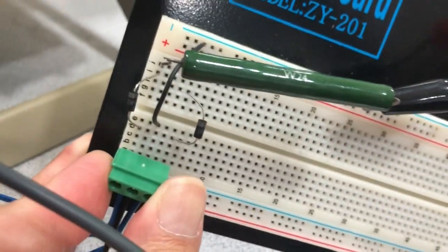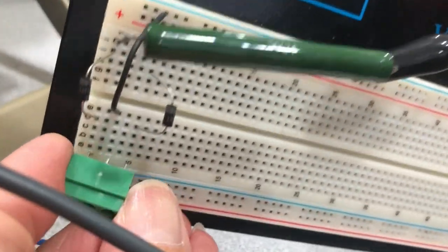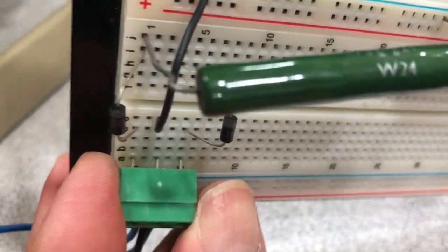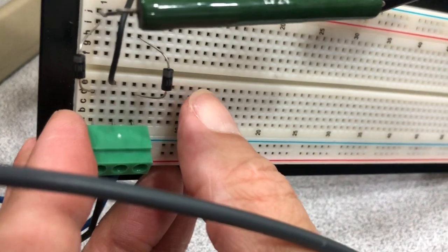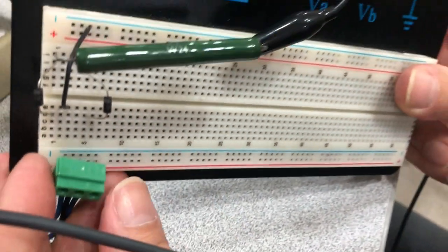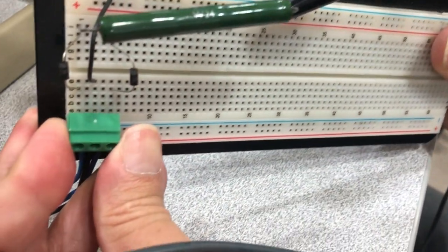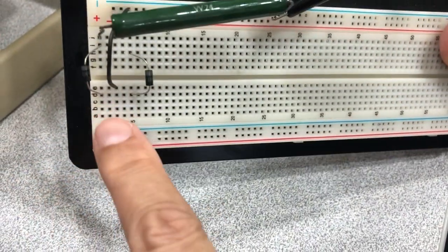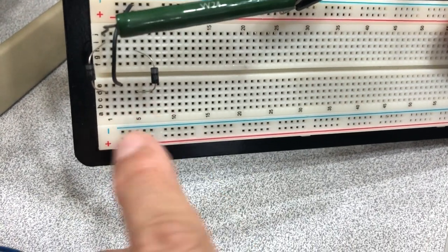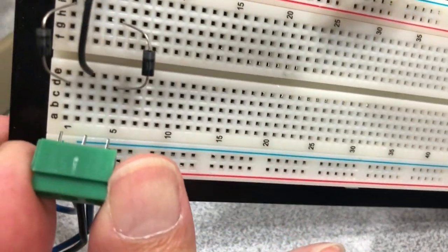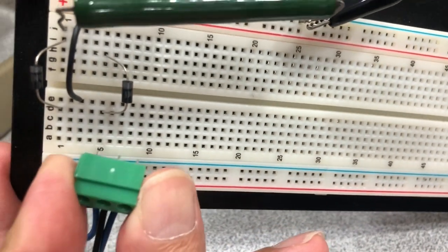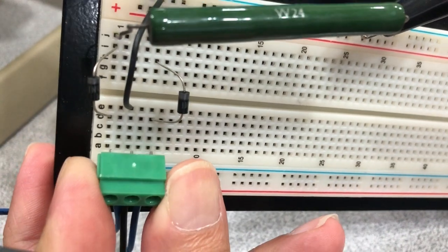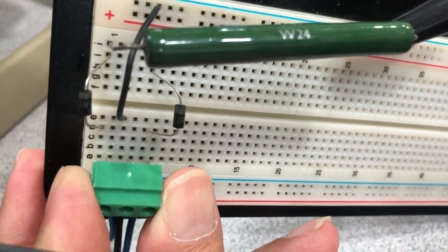The center tap, I have to skip one to reach my center tap because the pins here are spaced 0.2 inch, since the spacing between this hole and this hole, vertically or horizontally, is 0.1 inch, American standard. So I have 3 wires and I know where they're located. Basically, if you look at these numbers, it's 1, 3, and 5. So this is plugged in on 1, 3, and 5, but they only label 1, 5, 10. So you know which column it is. It's column 1, 3, and 5. So this is my AC in.